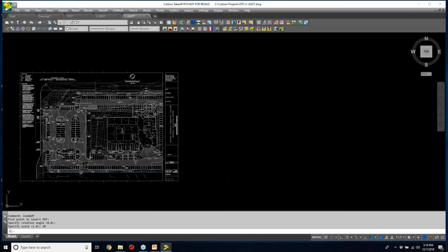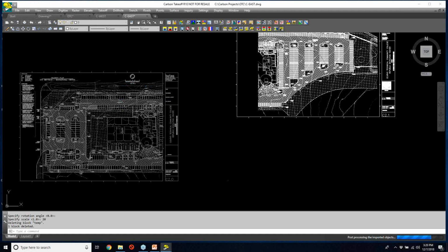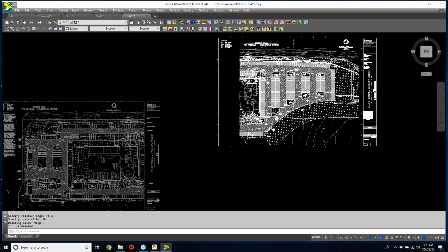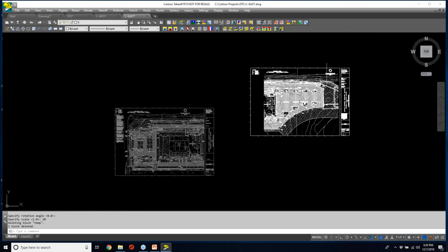And just to reiterate a topic I mentioned in the previous presentation on Tuesday: one of the things I always like to do, and I haven't done it, me getting into bad habits here, is check the distance of bar scales, because sometimes PDFs might have been replotted into different sheet sizes. As you bring those PDFs in, I would always encourage you to double check things, because invariably I've seen clients given a B size plot, for example, that might have been exaggerated up to a D size or vice versa. So I would always encourage good practice to make sure you are getting the proper dimensions, and make sure it's been scaled appropriately to the size indicated by the bar scale.